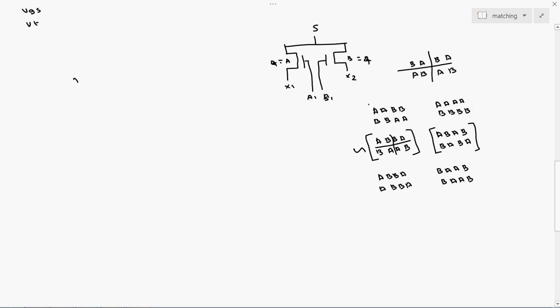Suppose A is equal to 2 and B is equal to 2. We have to draw for X and Y directions. See, A, B, B, A. So this is the best pattern. The common point between this B and this B is here, and this A and this A is here. Somewhere here. So this is common centroid based matching.